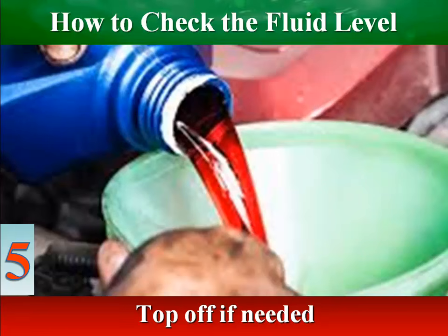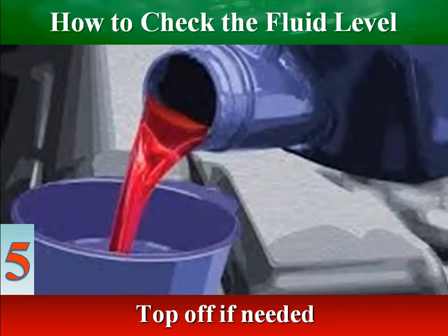If the fluid is low, use the correct type of transmission fluid, refer to your owner's manual, to top it off, ensuring not to overfill.